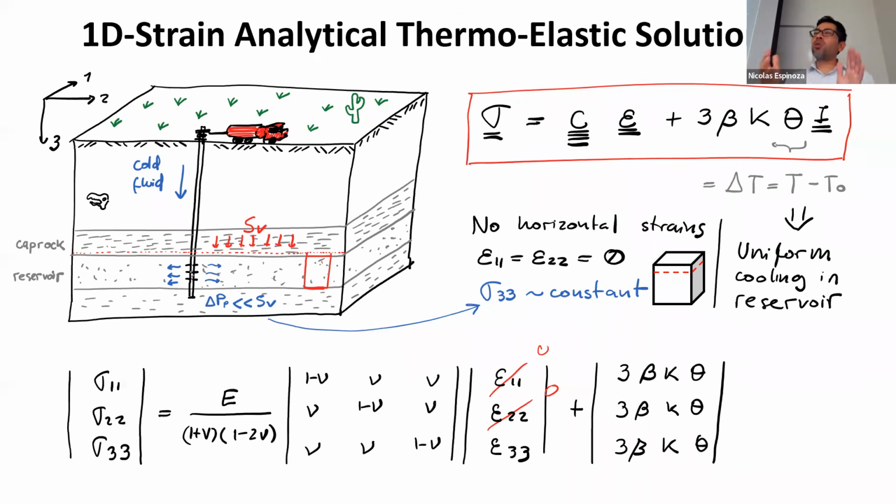And probably it's easier to imagine this as similar to those basalt columns. If you have an entire reservoir that is trying to shrink because of temperature at the same time, then there is no room for horizontal strains, because everything tries to shrink at the same time. No one can shrink. And that results, instead of a thermal strain, in a thermal stress, or in this case, a destress. That's why these horizontal strains are 0.